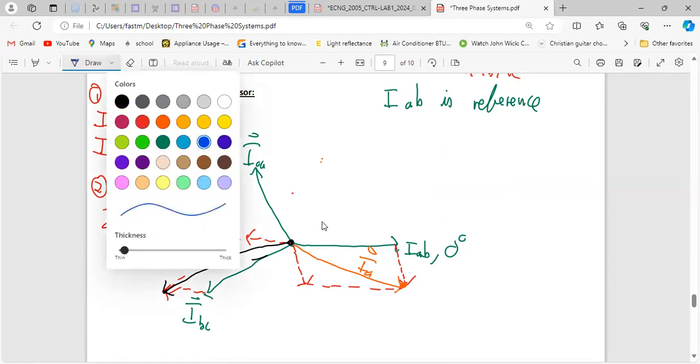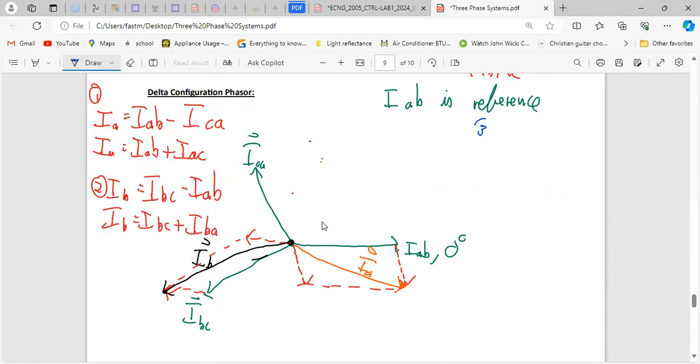And the last one, I will draw it up here because of space. IC. So IC would just equal your ICA plus your ICB. That's right, and it's another way that's easier for me to plot. So ICB would just be the flip of this piece here. So just draw that going up like this, not too long. Connect the other parallel piece to it. So no matter which side they start with first, they are both going to be parallel to each other. It really doesn't matter, and you just connect the two. So this here is going to connect from this here, draw it up.